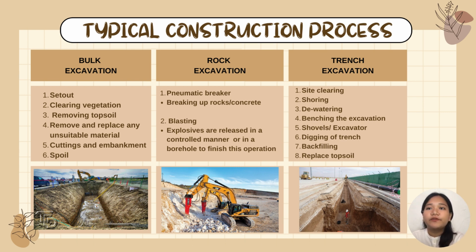Finally, trench excavations are narrow excavations that are typically used for strip foundations and buried services like cables and pipelines. To prevent collapse, the trench might be constructed vertical, slanted, or stepped. A trench excavation for rainwater drainage should achieve a 1 in 80 gradient, which equals 1.25 cm in 1 meter. For this reason, an excavator must apply as much trial and error work to meet the requirement of the finishing level.